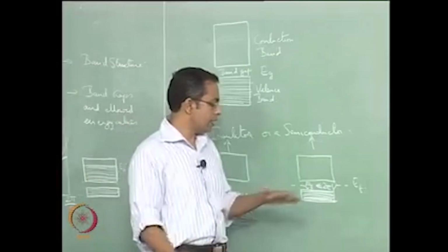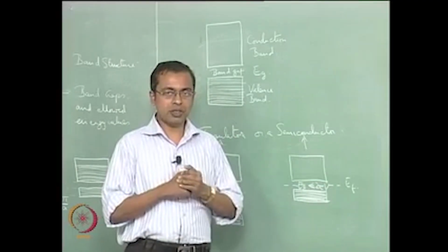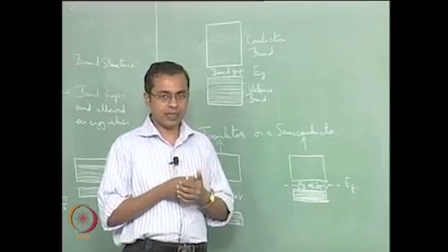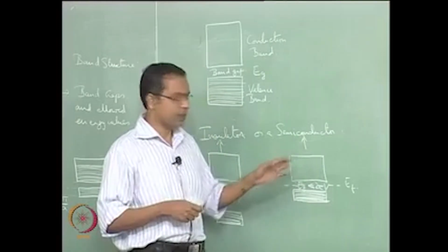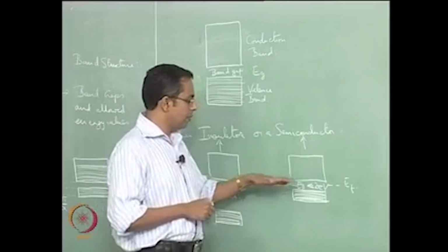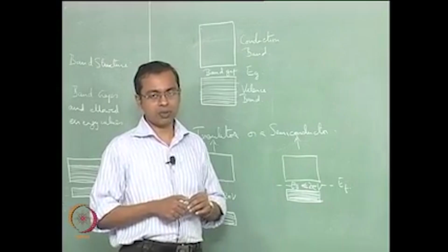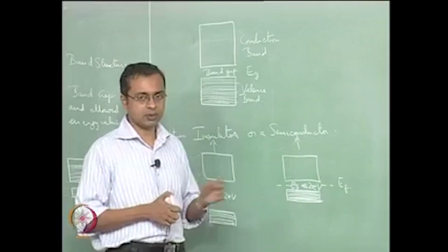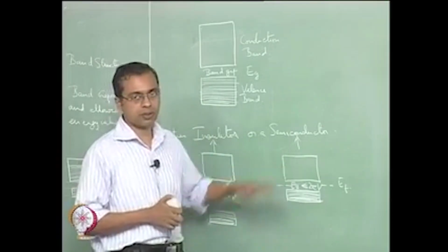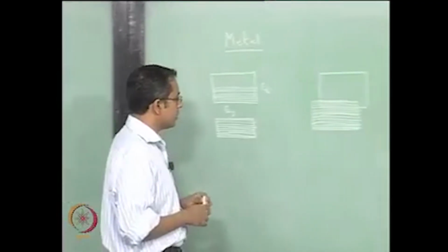And also the Fermi energy, of course, as I mentioned, conveys to you what can or cannot be done in the system. So therefore, when you dope, these are all the intrinsic semiconductors, we will see that in our next class, but basically when you dope this system, effectively you are raising or lowering the Fermi energy of the system. So that is effectively what you are doing. Okay, so this is the way in which it occurs.